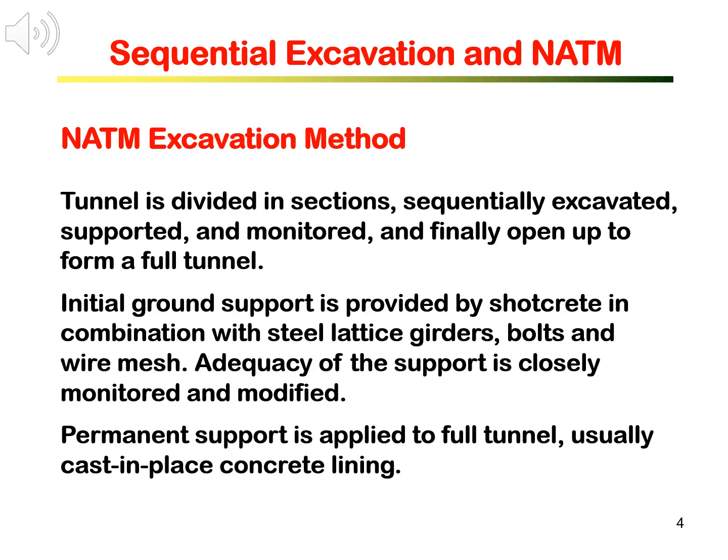NATM, as an excavation method, involves the following excavation steps. First, tunnel is divided into sections, sequentially excavated and supported with primary support. The primary support is closely monitored and modified if required. Finally, sections are opened up to form a full tunnel.